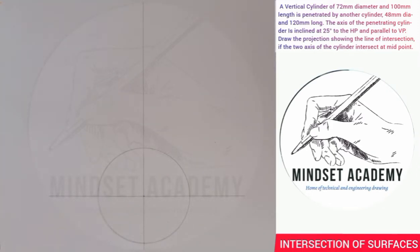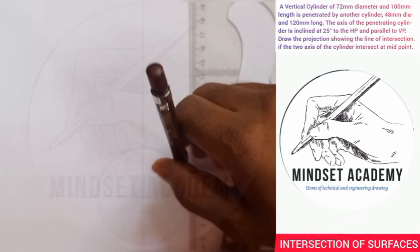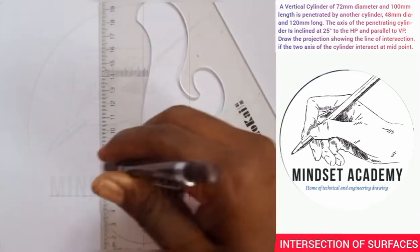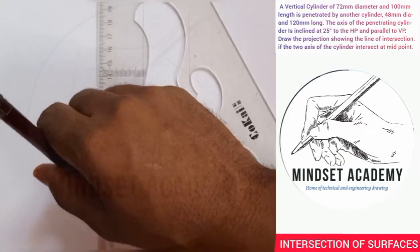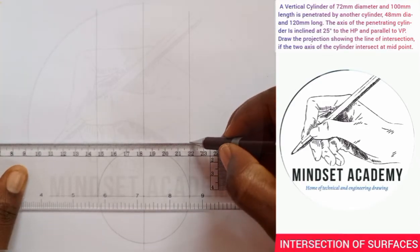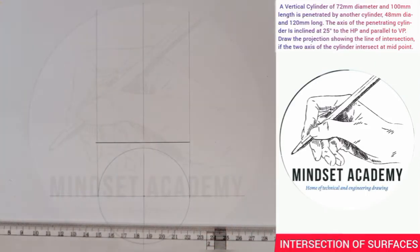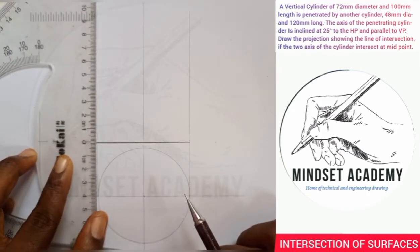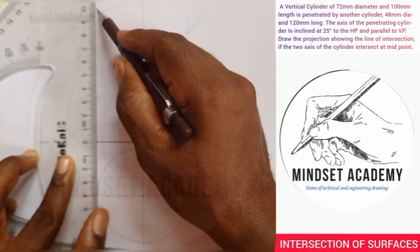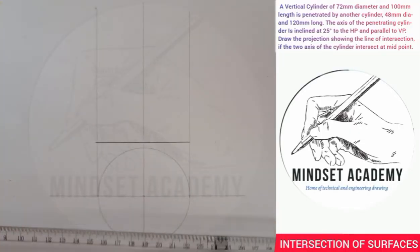Now after doing that, I'm going to project to get the elevation of it. So I project the ends of this cylinder in this manner, first of all using faint lines. You don't allow it to touch the base of the plan, and the height given will cover the height of 100 millimeter length. So I'm going to measure 100 millimeter from this point, from 0 to 100, and I'm going to close it up in this fashion.